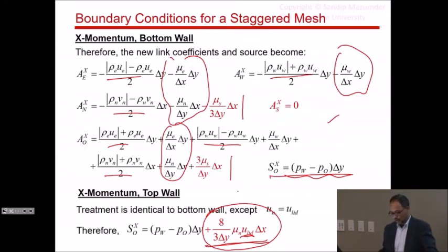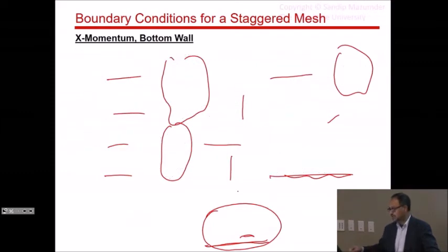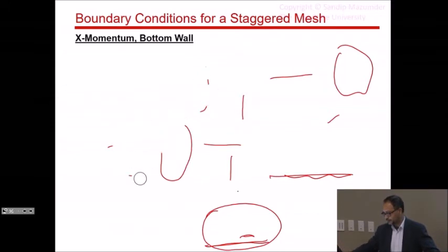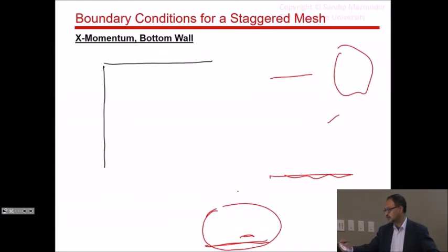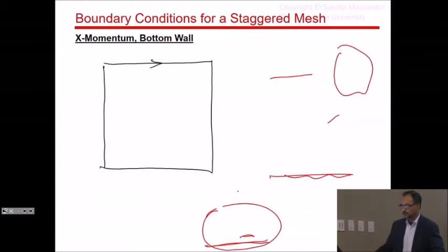Okay? So the very first time you solve your momentum equation, let me draw a picture here. So here's my cavity. Okay, here's my U lid. And if I asked you to plot U velocity contours on this, right after you've solved the X momentum equation with initial guess of U equal to 0, V equal to 0, P equal to 0, what do you think you'll get?